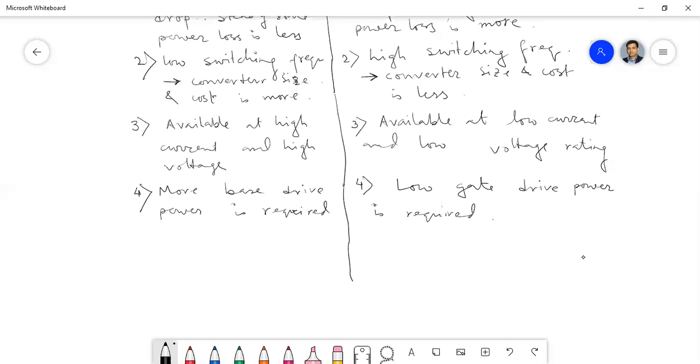Okay, because the power MOSFET offers very high input impedance because it has a silicon dioxide layer, which is insulating material by nature. So that is placed between the metal contact of source and the other substrates. Now when the gate current flows, that is very less because in between you have an insulating material.